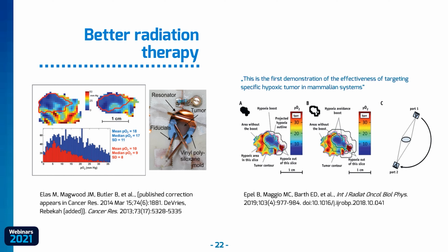For the experiment, the authors used a 250 MHz pulse imager with a new transmit-receive switch, enabling 1 kilowatt peak-to-peak pulse power operation with a reflection resonator.